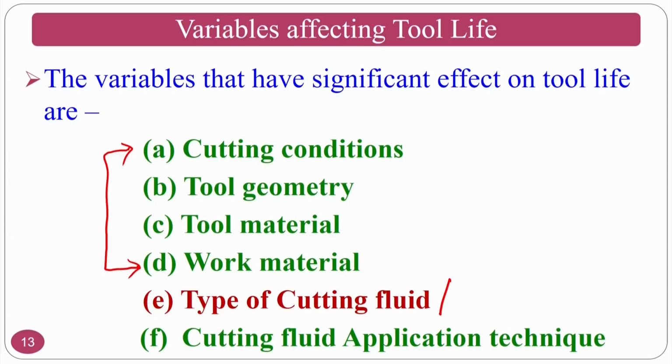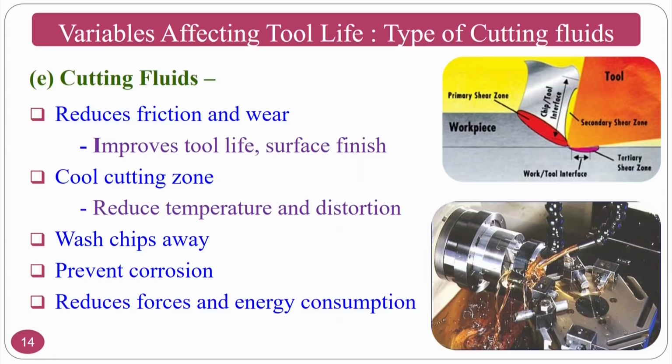As we see, our course is on machining fluids, and we will come elaboratively to the cutting fluids in upcoming classes. However, I will give you just a slight glimpse. The basic function of cutting fluids, if you see, is that it reduces friction and wear and cools the cutting zone, that is nothing but cooling and lubrication.